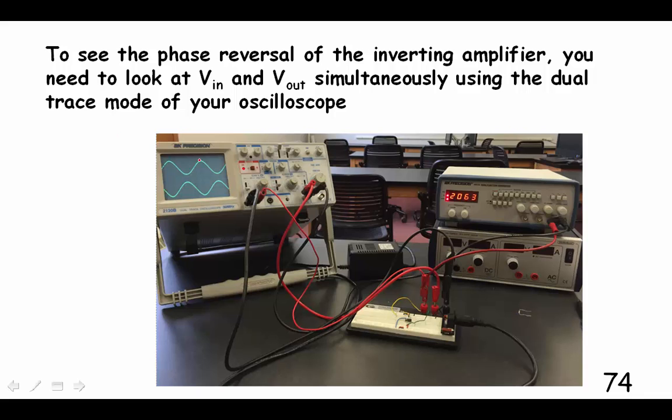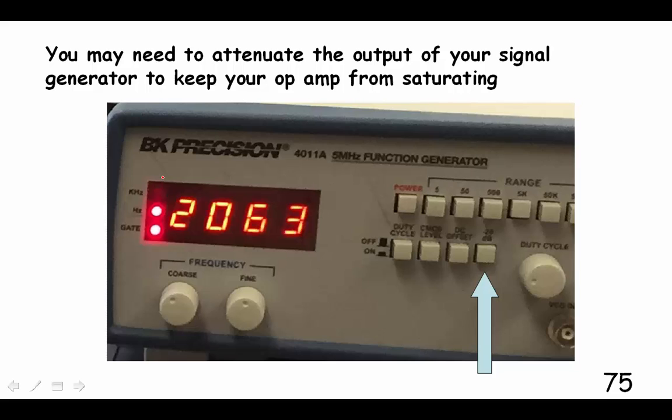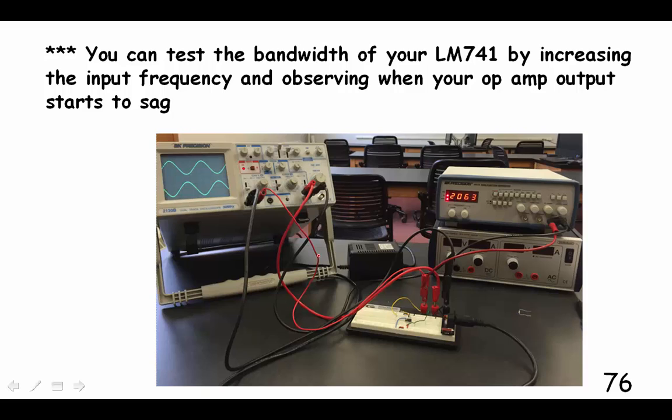So in order to see the phase, I have to look at the input and the output simultaneously using the dual trace mode of our oscilloscope. So I've set that to dual trace so I can see both of the signals on the screen at the same time, and you'll have to do that in lab. You probably will have to push in that negative 20 dB button on your function generator because the output is too hot and it's going to saturate your op amp if you don't do that.